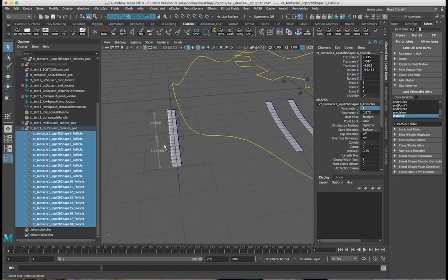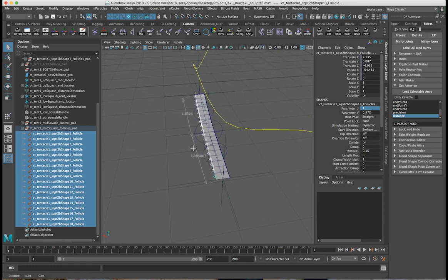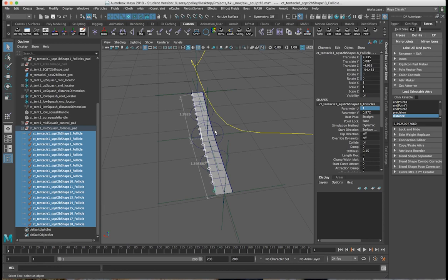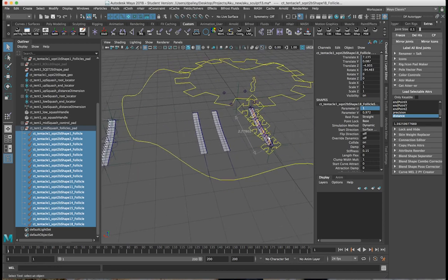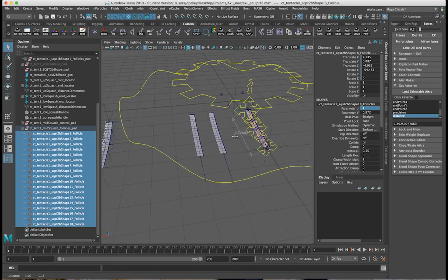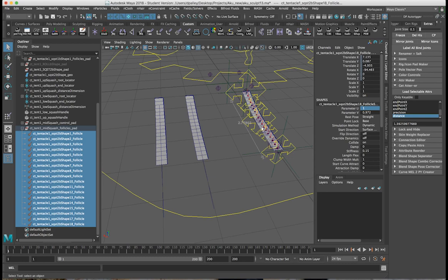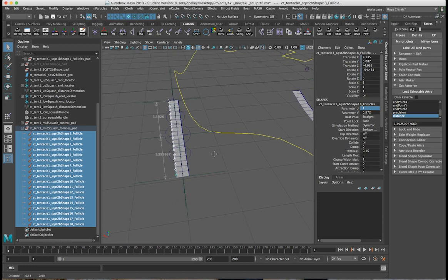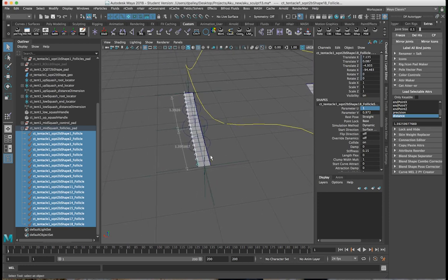And then at this point, just like we did the last one, we're going to convert the distance from this point to the center of the ribbon and convert that into the scale of these joints. Now, the scale is already connected to the other system for the all squash that we did right over here. So we're going to have to combine those two together.